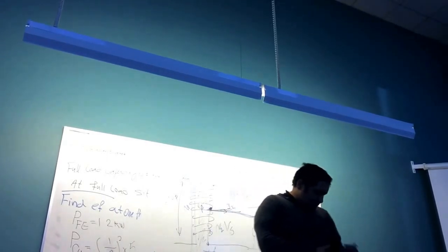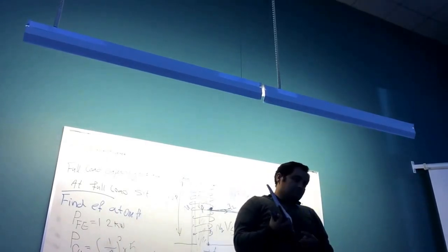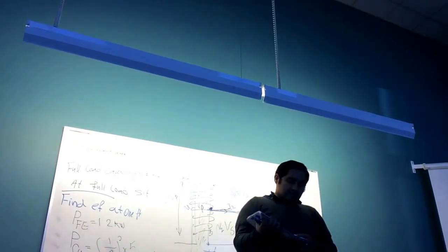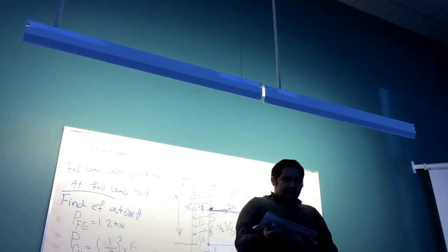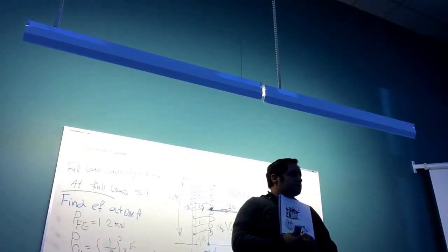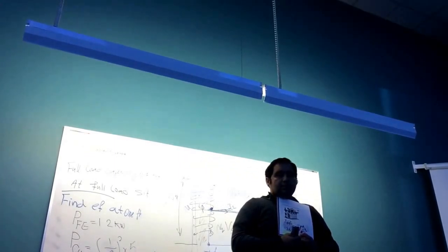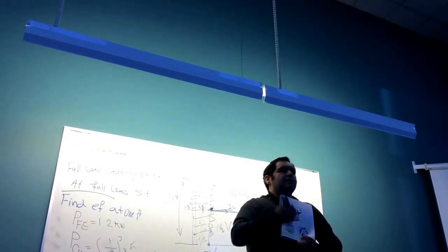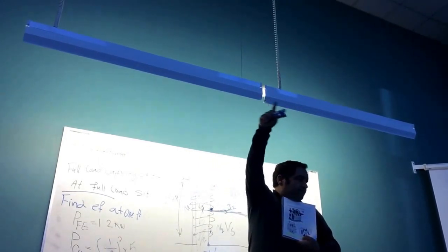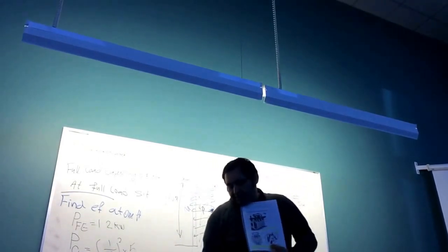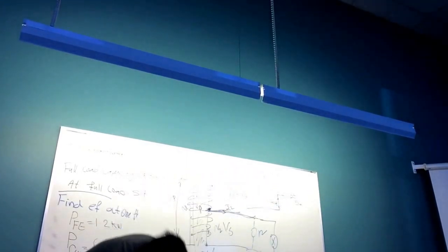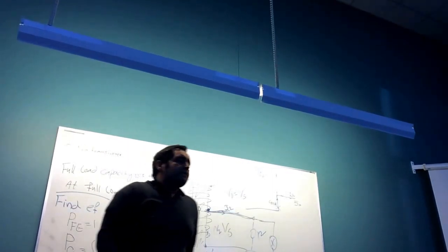So how does it work? How does it look? You can see how it looks. Basically we have some tubes that let the oil get circulated, and we have some tubes that let the hot oil go back to the reservoir. And we have a gauge, and the gauge shows us how much oil we have in the transformer, because sometimes the oil is leaking. So we need to know whether we have enough oil or not.